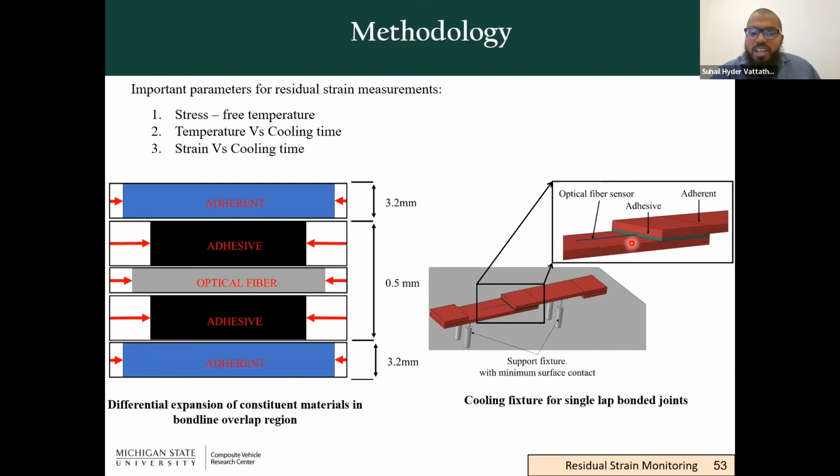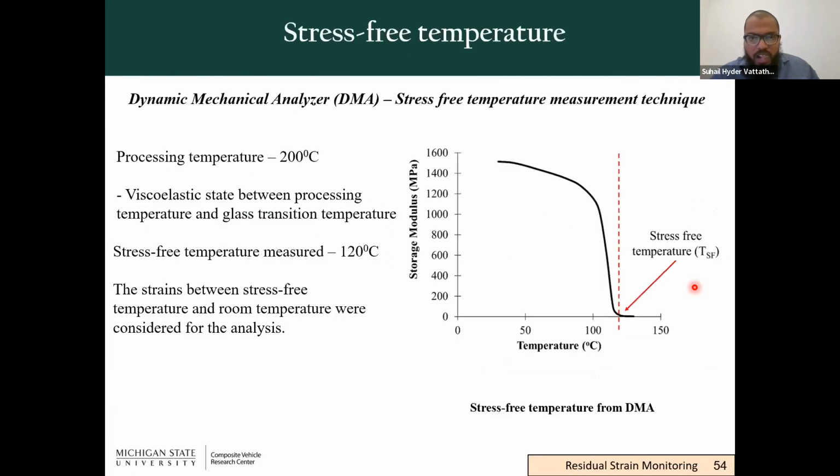And from the strains, what we did was we actually made a computational model, and that model was experimentally validated by matching the strains that we observed using the experiments. And then using the computational model, we can see what was the magnitude of residual stresses within the adhesive. So that was the plan.